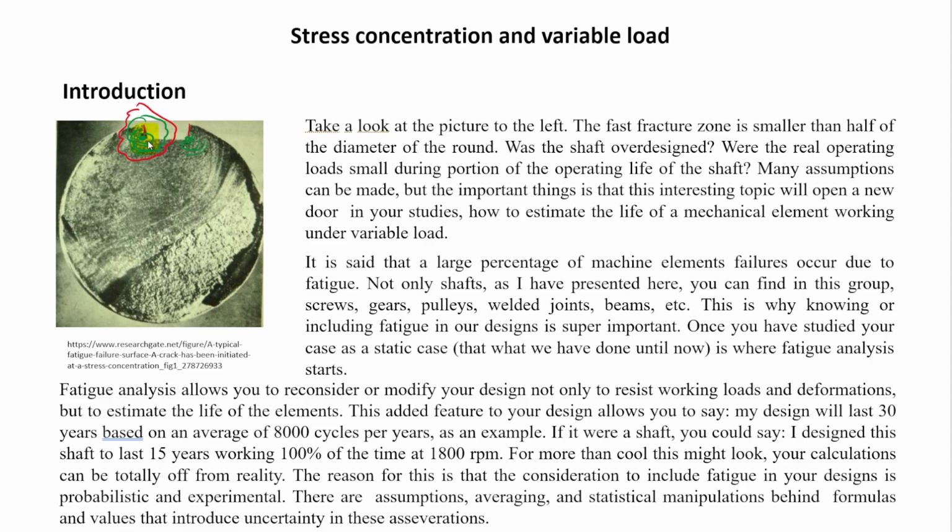And what's going to happen is that as the stress is higher, it is possible that this increased stress in that area surpasses the yield strength of the material, and then it deforms, or it surpasses, in that small spot, the ultimate strength of the material, and then it creates a micro crack, a small crack there. And then that crack is the point of initiation for what comes next, which is the fatigue failure or complete rupture of the whole shaft.